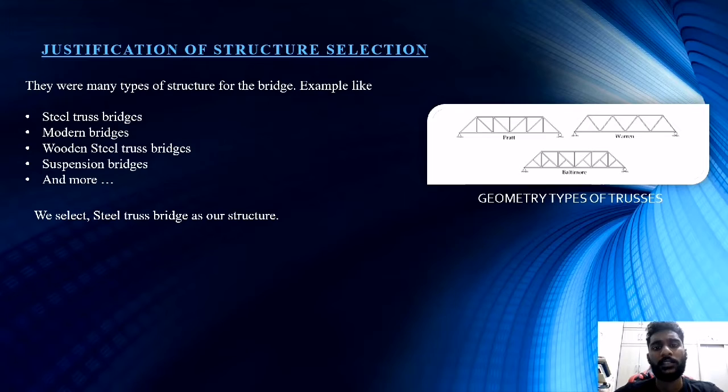As a justification, the steel trusses took advantage of the axial stress capacity of the bar element, creating bridges with longer spans, low weight, and enough stiffness to withstand higher loads due to the large number of geometries that can be created with trusses. There are possible arrangements with the bar elements taking advantage of the tension and compression stress capacities.